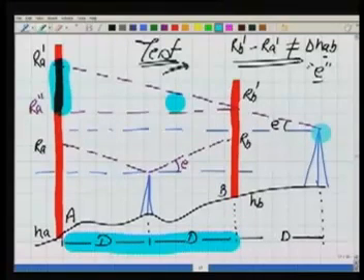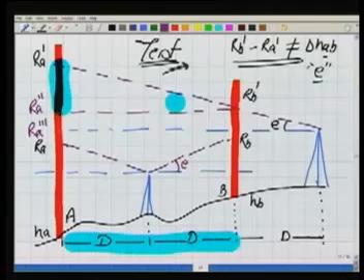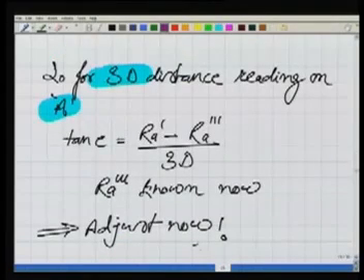because right now my instrument is here, okay, and my instrument is looking in this direction. Had my instrument looked in horizontal direction, where should I have bisected? I should have bisected at this point. If I write this point as this RA triple dash, what should be the observation at RA triple dash? This we can easily find because we know now the value of E.